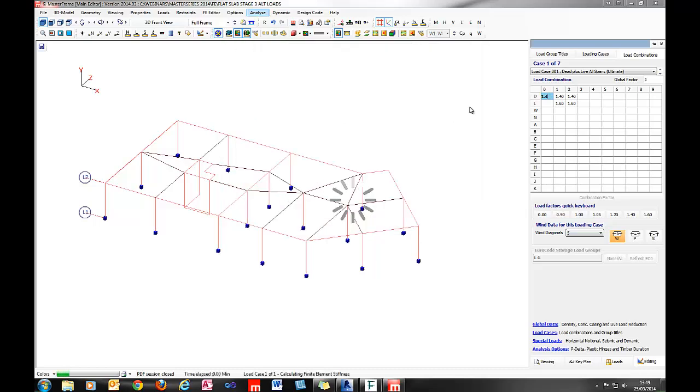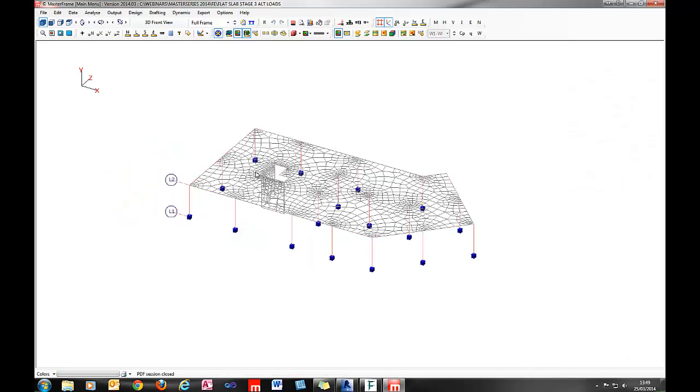So analyzing now will allow us to continue without that error. So that's just something that you're going to find very, very useful. Previously, people would have set up the separate alternate load set 0 for all their walls, but now you don't have to do that with the default option.